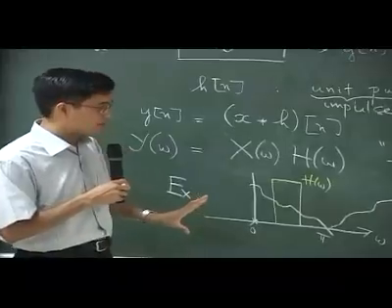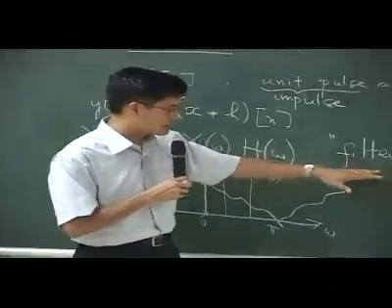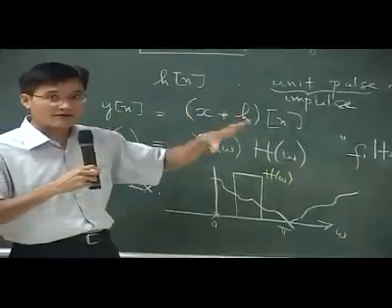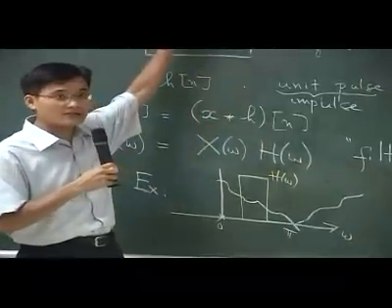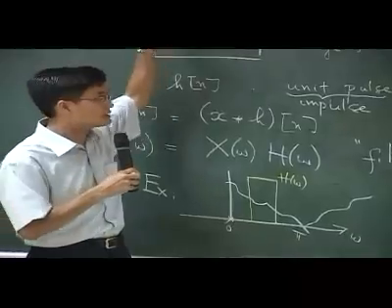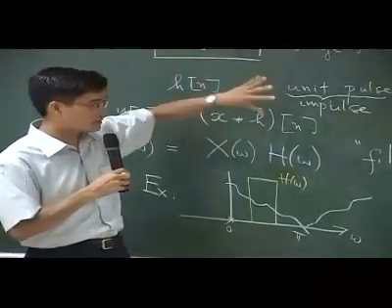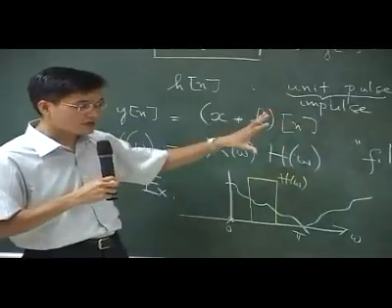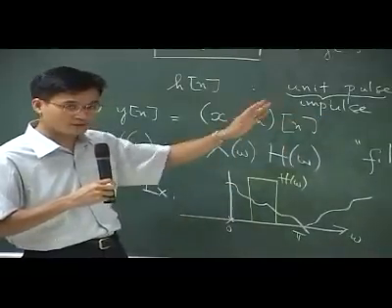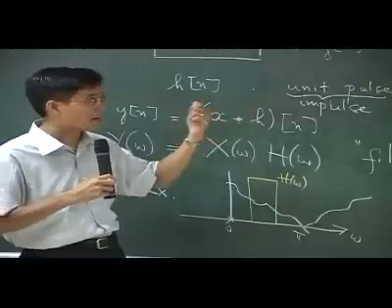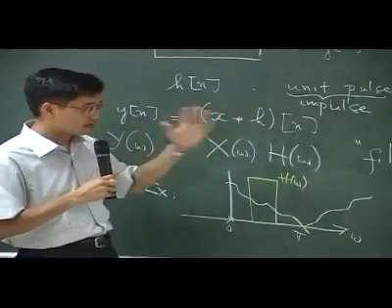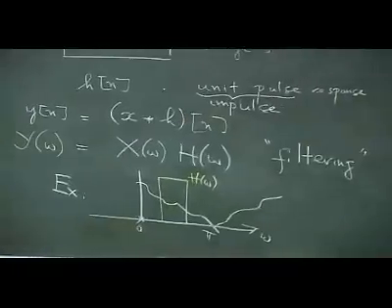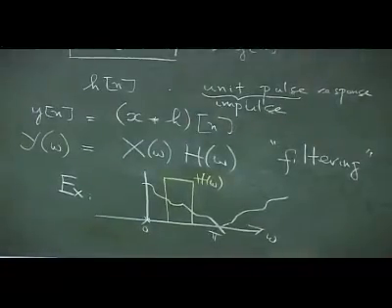But I need you to keep in mind that even though it looks like a filter, it is a very general LTI system. Any linear time invariant system can be considered as a filter. Okay, so even though you go out there and there's nothing to be filtered, you need to design some linear time invariant system, you simply design a filter. Okay, all right. So with that perspective in mind, let's move on here.